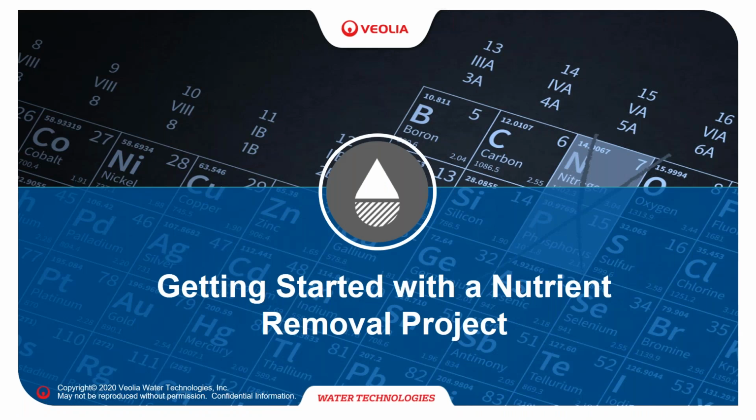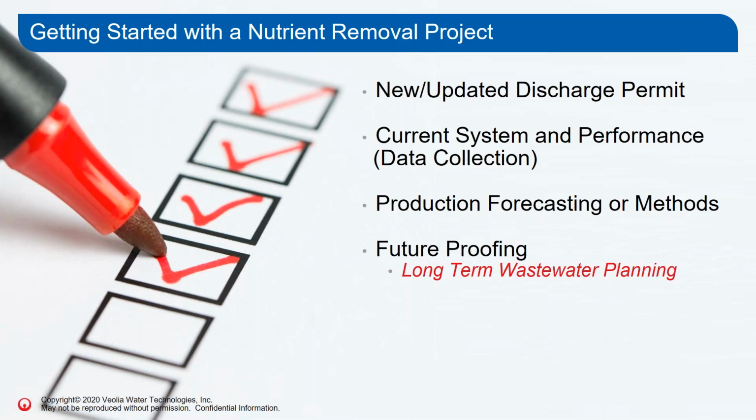So what would get you started with a nutrient removal project? Let's go through our checklist. As I presented in the beginning, if you operate wastewater treatment plants in industrial facilities, you're probably facing renewed permits right now. A lot of facilities are looking at renewal of the permits, and the new permits that are coming starting this year and into 2023 will have much higher nitrogen and phosphorus limits. So while before you probably didn't have to think about it, for a lot of our clients, they now have to consider nitrogen and phosphorus even without changing anything in their system.